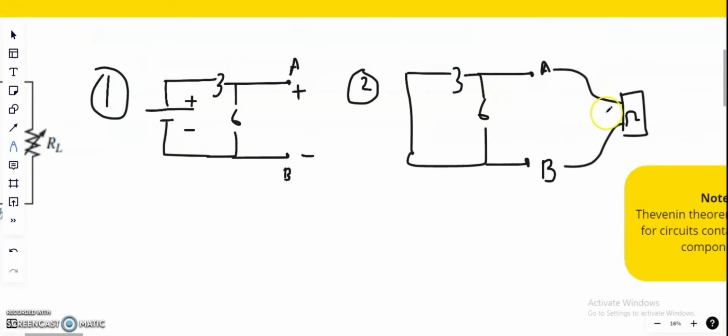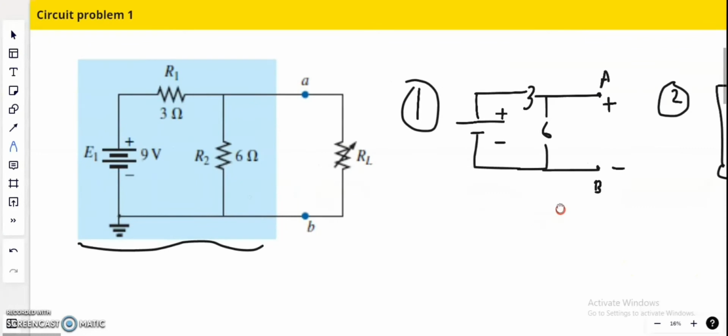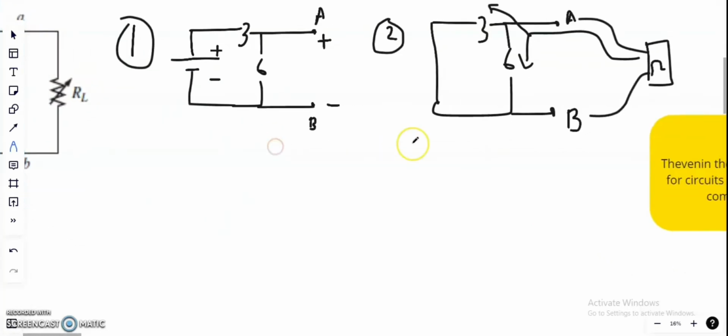But theoretically, we need to calculate our total equivalent resistance. From the diagram, we can see that the current from the ohmmeter travels through the wire and gets divided between the two resistors. So we can say that R1 and R2 are in parallel. To find the equivalent resistance, the formula for adding parallel resistors is 1/RT = 1/R1 + 1/R2.